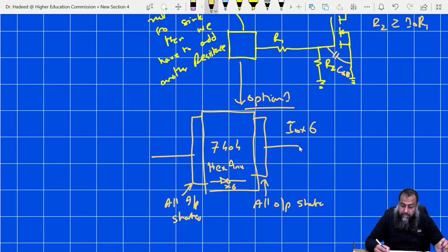But again, the problem is that most of the time this is not a feasible solution, because it may not be able to suffice for the switching conditions, and therefore we require something which is able to level shift up the input voltage, so that the device can go deep into the saturation region. This logic IC is usually able to work at plus 5 volt, and we have 2 pins, one connected with plus 5 volt and the other grounded, and therefore it is not capable of stepping up the level shift. It is not able to shift the level up for the gate to the source voltage.